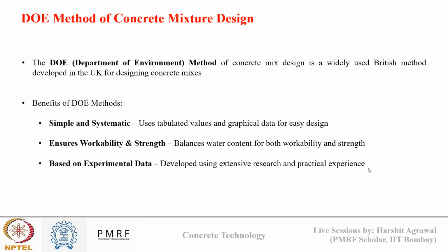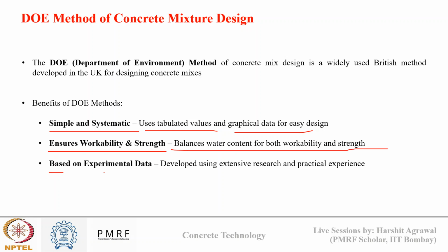Now, what are the benefits of the DOE method which make it a widely used method? These benefits are: DOE method is simple and systematic, so it uses tabulated values and graphical data for easy designing. Second, it ensures workability and strength, so it balances water content for both workability and strength, and it is based on experimental data. Whatever charts have been developed in the DOE method were developed using extensive research and practical experience.